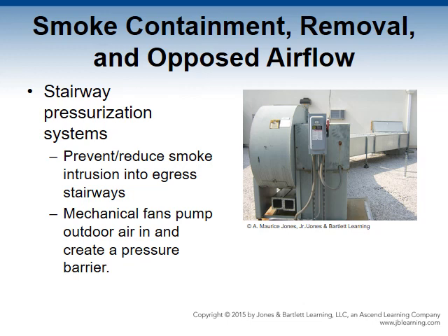Stairway pressurization systems prevent or substantially reduce smoke intrusion into egress stairways so occupants can use them to exit and firefighters can stage in a relatively smoke-free environment. Mechanical fans pump 100% outdoor air into the stairway, creating a pressurized barrier to prevent the smoke from migrating in. These systems perform best when they are combined with smoke removal or relief on affected fire floors.